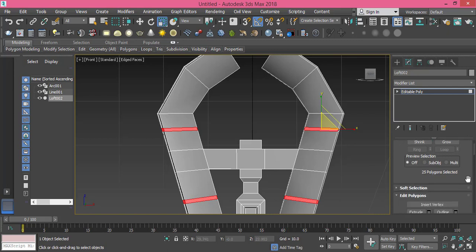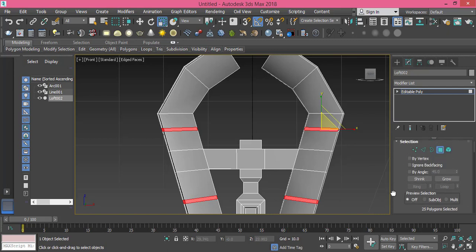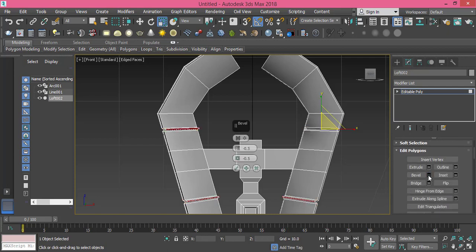Now we need to do a bevel, not an extrusion. We do a bevel with the value of 1 and a value of plus, not minus 2, so we just remove that minus, and we make sure we're working on local normal.